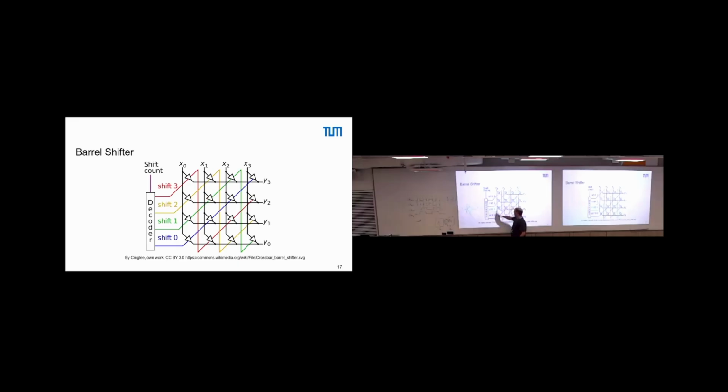It's just that you understand this here is effectively such a gate. If we switch on that side, we transfer. If we don't switch, we don't transfer. Okay? Which part? This one here. So this is a pass gate. We have an NMOS, we have a PMOS, we have a select signal. If the select signal goes high, we have a channel from input to output.